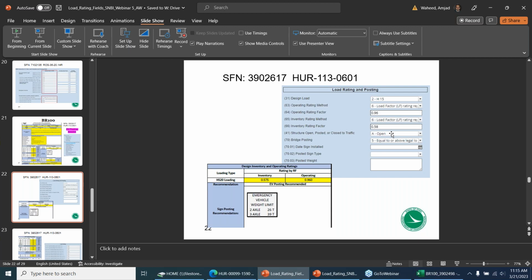There are different bridge definitions in Ohio. For example, a Federal Bridge is more than 20 feet and an Ohio Bridge is 10 feet or more. But SNBI has been adopted for all the bridges in Ohio. So any structure which is defined as a bridge and has a structure file number, the same requirements are for all the load rating of all the bridges carrying heavy highway loads.